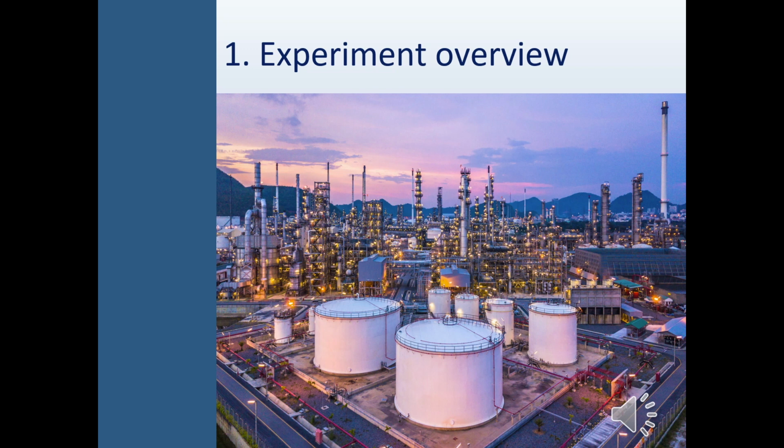Important parameters that influence head loss include pipe diameter, the flow rates of the fluid, surface roughness of the pipe network, and the types of fittings. Furthermore, the altitude, position, and the length of the pipes also affect pressure drop. With this understanding and application in industry, product quality can be manipulated and economic feasibility can be maximized.